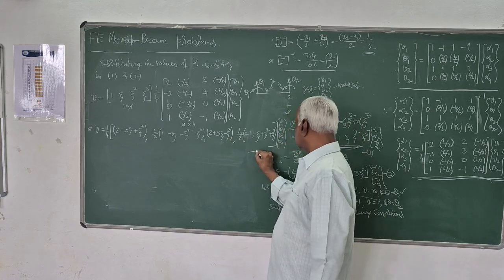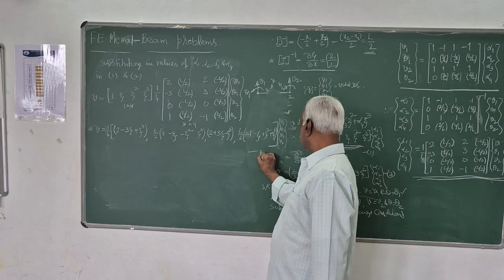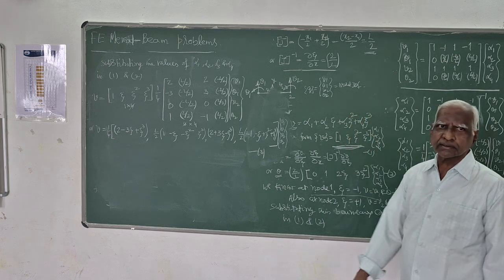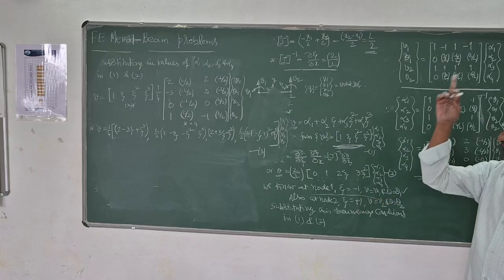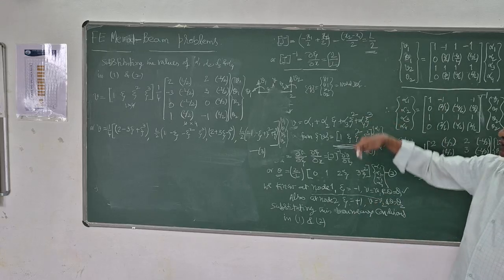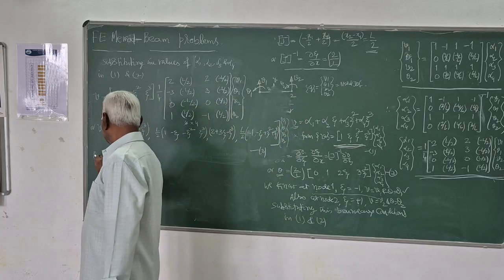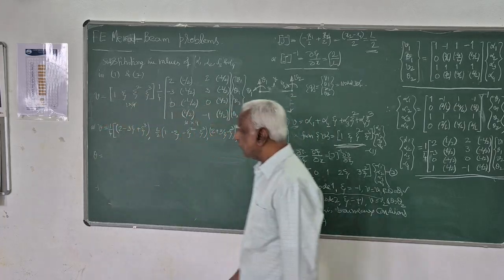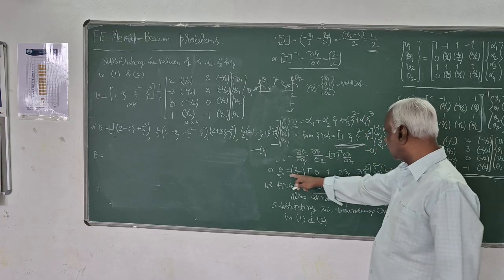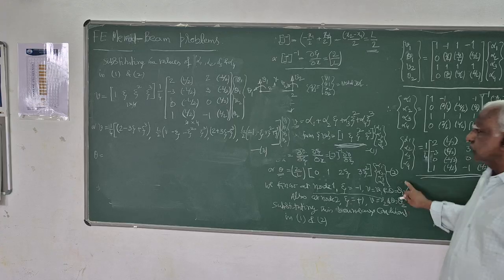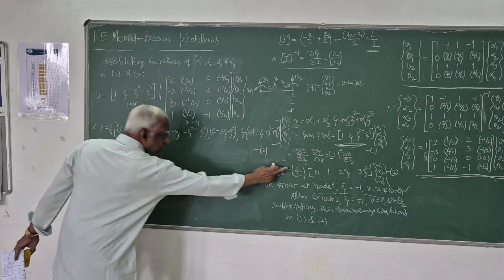You call this equation 1, 2, 3. This is the third equation. This is the actual equation for displacement, the vertical displacement at any point in the element. Similarly, the slope at any point is given by substituting these values of alpha 1, alpha 2, alpha 3, alpha 4 in equation 2. You will get this is nothing but 2 by L